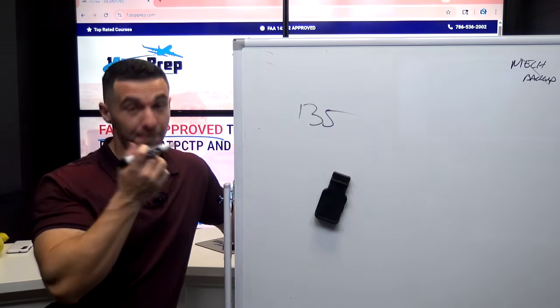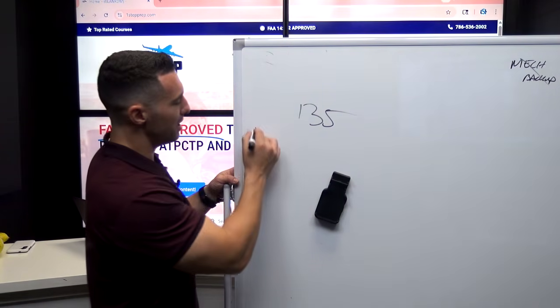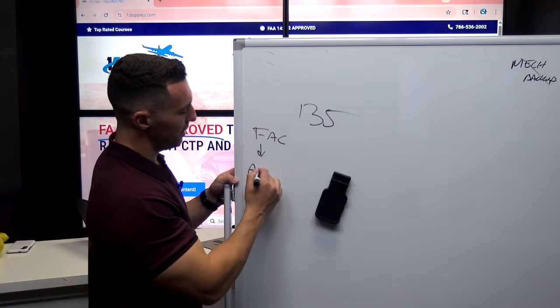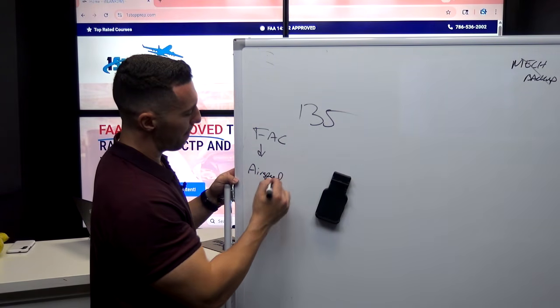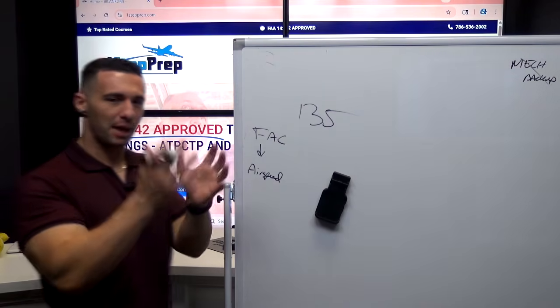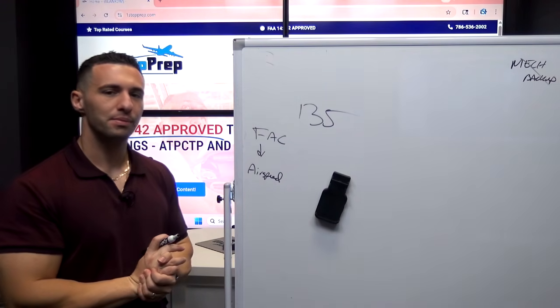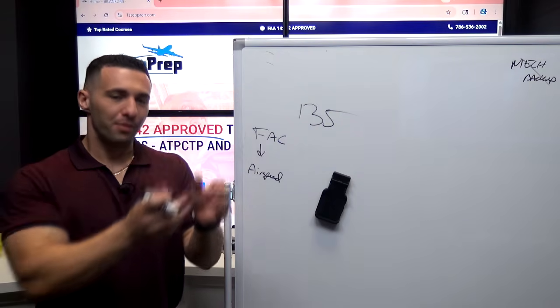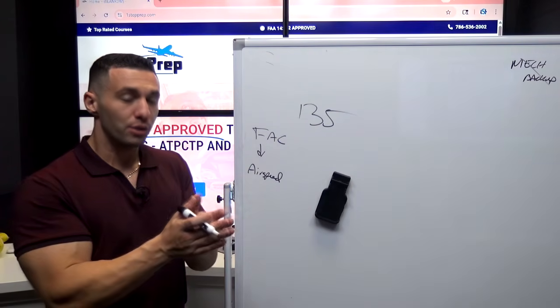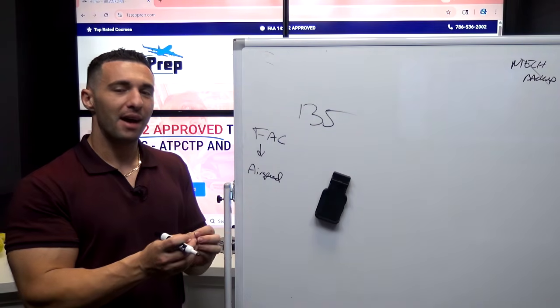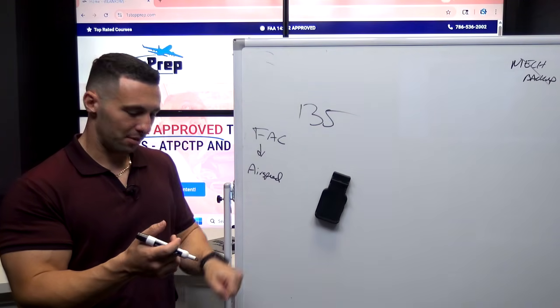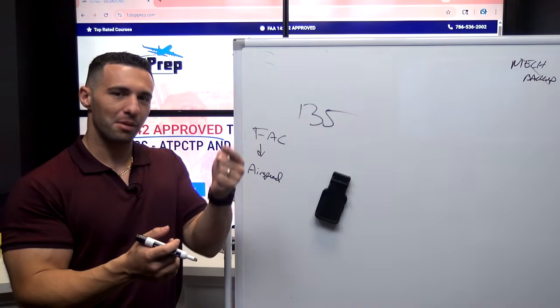So then the FAC, the flight augmentation computer, remember earlier we said the FAC is controlling the airspeed envelope. It's giving that presentation of the airspeed envelope. And so with that VLS presentation that you see there, you'll notice that if I have flaps 0 and I put the spoilers out, VLS comes up.